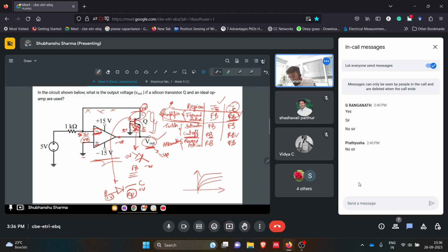Forward bias. And then, since we have connected feedback, because of this feedback it will start balancing its output. So what will happen? The virtual short concept will come into picture. So this will slowly start becoming 0 volts, and once it becomes 0 volt, the base collector junction will come in reverse bias mode. That means this transistor is acting as an amplifier.